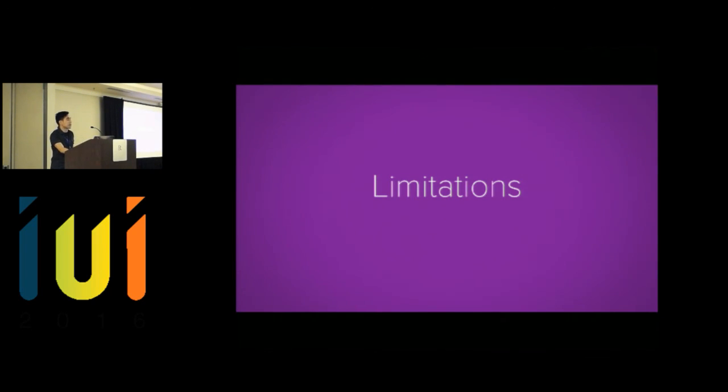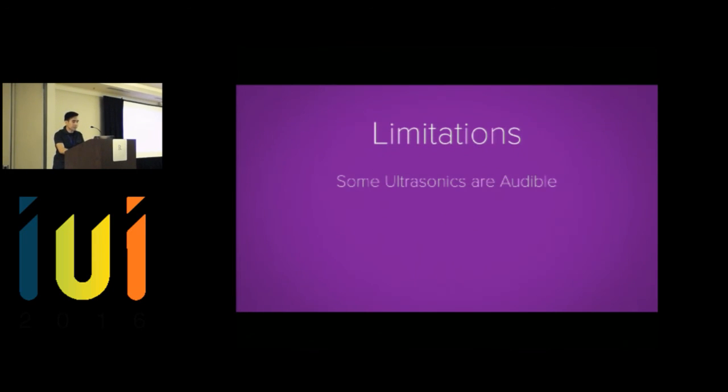So like all techniques, our approach has limitations. I'm going to go through them really quickly. First, ultrasound may be audible to some children and pets. And this is related to the second limitation, which is that most existing hardware has a sampling rate limit of 44 kilohertz. But as hardware improves, we can increase our ultrasonic frequency range beyond human hearing.